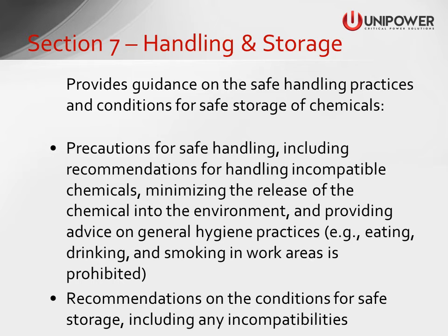Section 7 talks about handling and storage of chemicals. This section provides guidance on the safe handling practices and conditions for safe storage of chemicals. This section includes precautions on safe handling, including recommendations for handling incompatible chemicals, minimizing the release of the chemicals into the environment, and providing advice on general hygiene practices, including eating, drinking, and smoking in the workplace that is prohibited. Additionally, recommendations on the conditions for safe storage includes any incompatibilities.